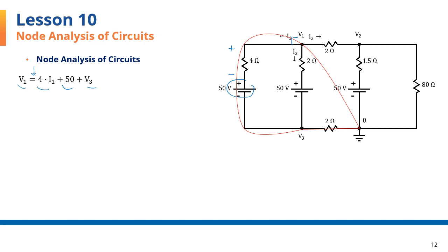The idea is to form an equation that will have in it only one of these three currents and as many of the unknown voltages that appear along the loop. For this first one, we have just the I1 as an unknown current, and the rest of them are the different voltages. Now we will go around a second loop, but this time after we go to node 1, we follow the path of I2 and back. And you see that here.